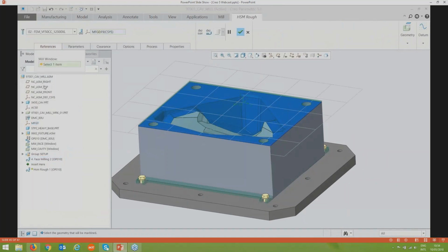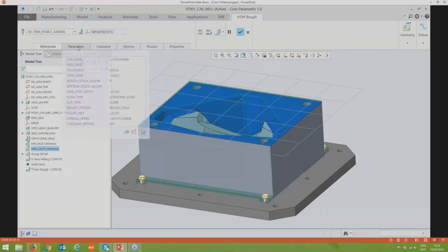So the keen-eyed among you there may have just noticed we've got a new section within the milling tab, okay, which is for high-speed machining. Okay. So a brand new set of tools here, and the first tool we're looking at is just going in, we're creating a roughing. Okay, so we're sort of boring out that material in the center there. Again, we've got all our parameters that we can go in and fill out. I've changed a few there, and the last one we'll go in and set is just a coolant operation. Okay, so or coolant option, and we'll just set that to a flood option.